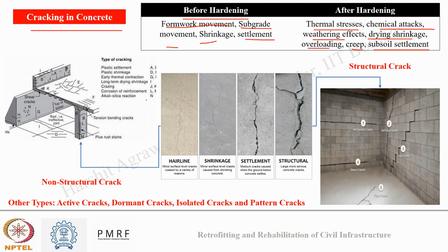So, structural cracks are those which result from improper design, overloading, foundation settlement, faulty construction practices. So, these are all the major cracks, okay, which occur due to the design phase of the structure. Now, these cracks can be seen in any orientation. It can be horizontal, vertical, diagonal, and even like a step. The same you can see in the image also.